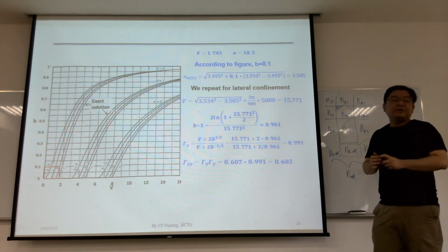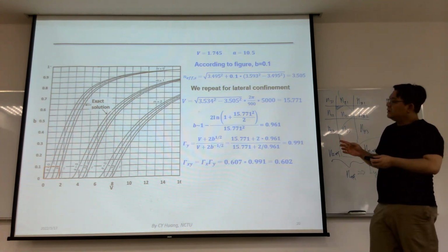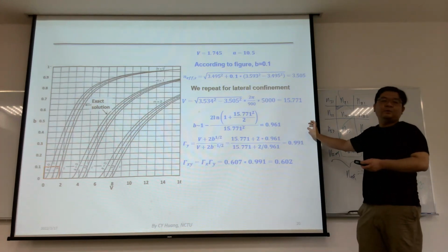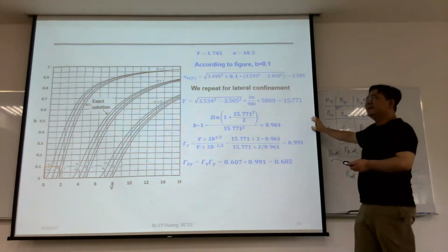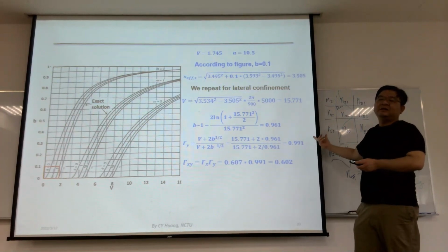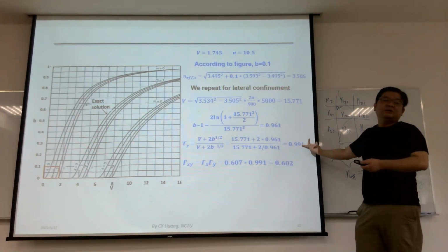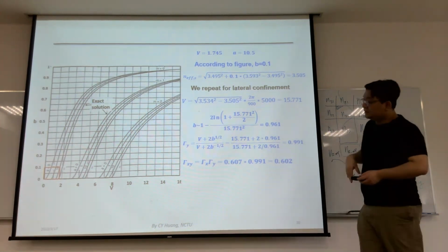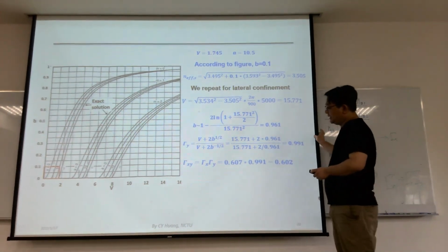A very narrow ridge will give you rather weak optical confinement in the lateral direction, so the threshold current density is usually higher. Well, that's a pretty simple explanation of it.